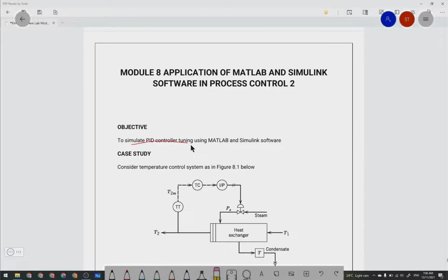A little bit different from the previous one, whereby we just decided the values of P, I, and D, and then tested three values of P: P1, P2, and P3. Same goes with I1, I2, and I3, and D1, D2, and D3. Here, we're going to find the PID values, but by doing a tuning whereby we can find these three values simultaneously at the same time, compared to trial and error for each value.